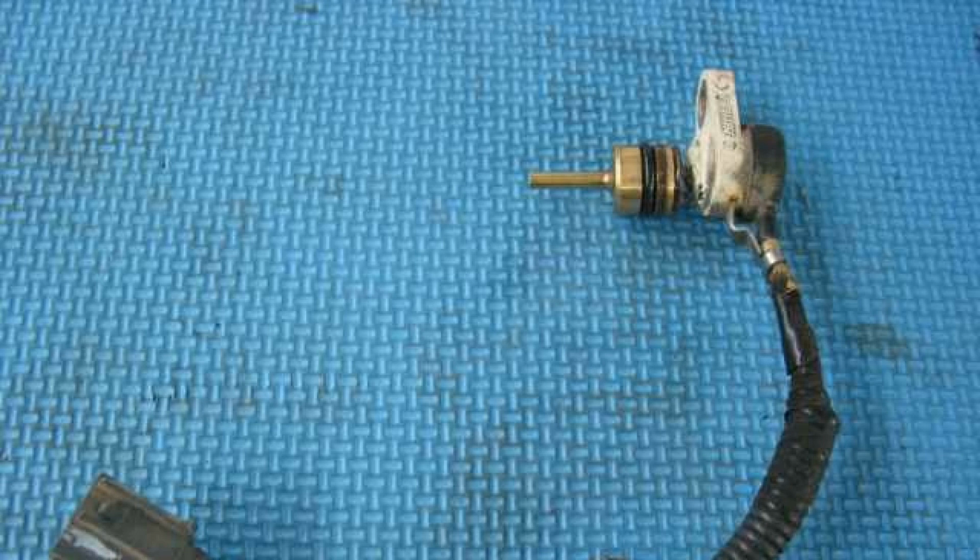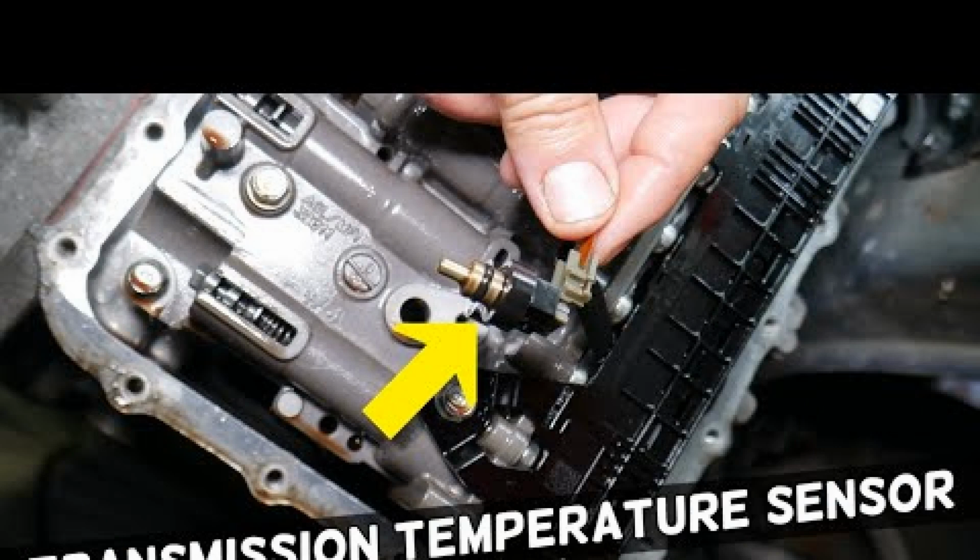An inadequate level can affect the temperature of the fluid, triggering code P0711. If necessary, adjust the fluid level and check the transmission system for leaks.